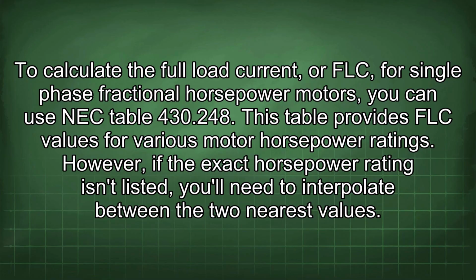To calculate the full load current, or FLC, for single-phase fractional horsepower motors, you can use NEC Table 430.248. This table provides FLC values for various motor horsepower ratings. However, if the exact horsepower rating isn't listed, you will need to interpolate between the two nearest values.